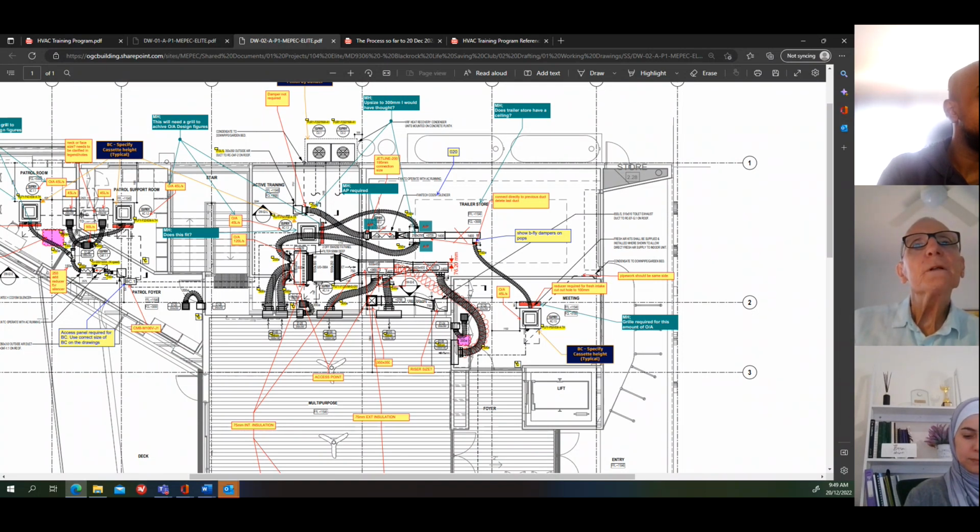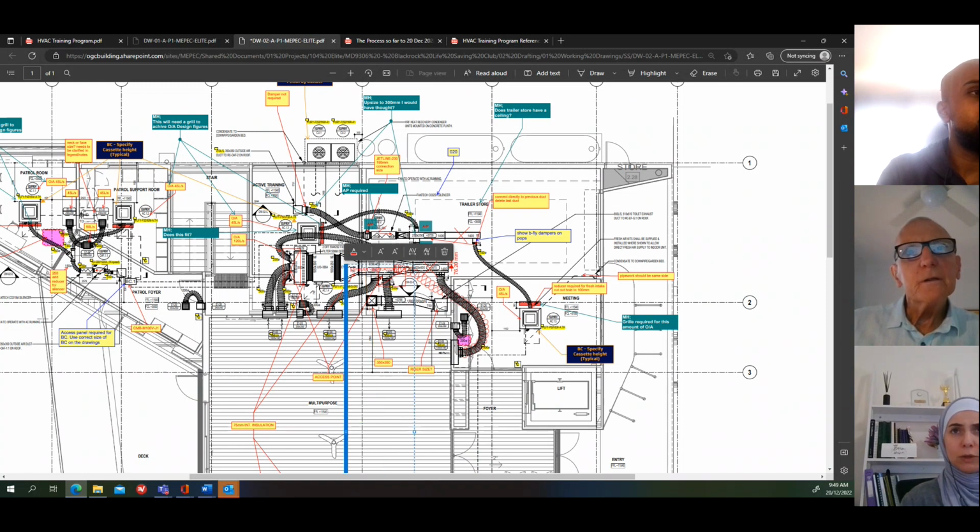Okay. Yeah. Now this drawing also shows, can you see that 1400 there? I'm just highlighting it there. That is the length of that piece of duct. So you don't get those sort of dimensions on a design drawing because it's not relevant. It doesn't matter. But in a workshop drawing, you do.